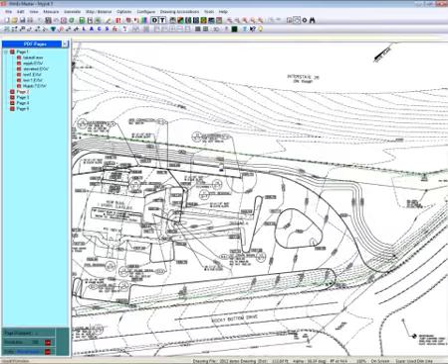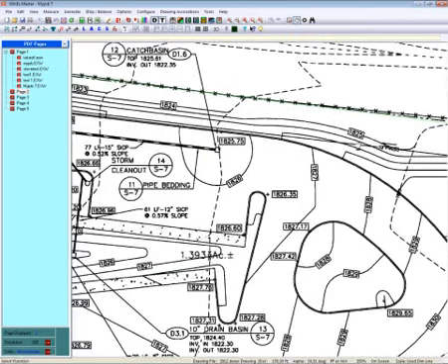If I zoom in here, you can see I'm crossing lines, I've got changes of directions, I've got elevation callouts, I've got numbers in here, and AccuTrace and AutoTrace, when you cross over lines, change directions, or come down to where you get the elevation callouts, it doesn't know what to do. It needs input from you. Does it need to jump to the outside of this? Does it need to jump to a number? Does it need to jump to one of these other lines?